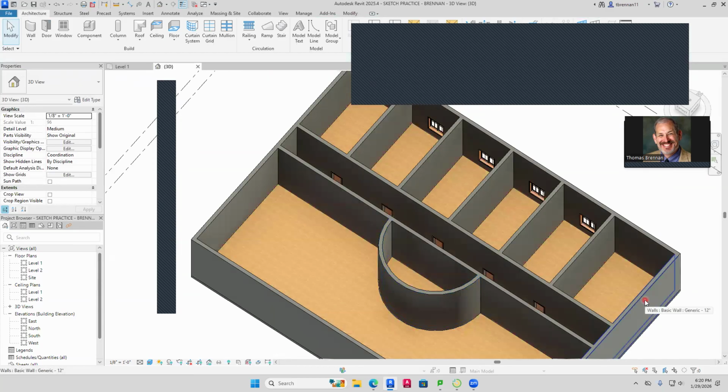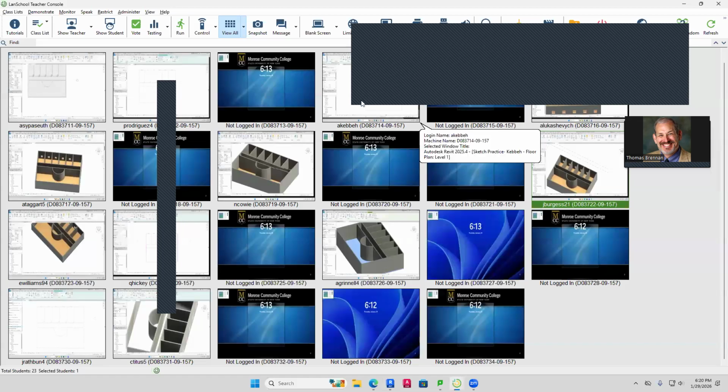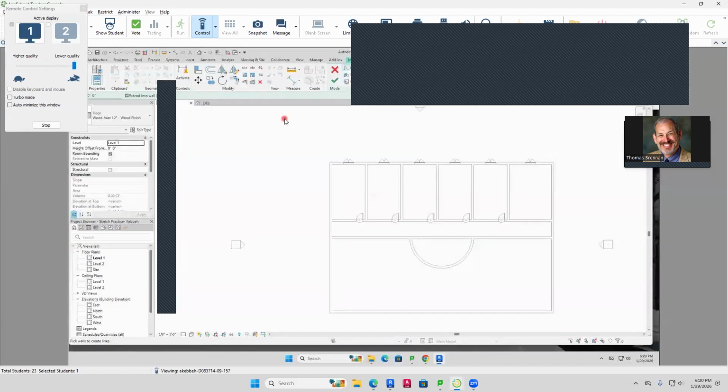Yes, sir. After you press joint, wood joint. Okay, yes, so you click on okay. So what you're gonna do is you're gonna click on the rectangle tool. Okay, so click on rectangle, then pick the far left top. Yep, click there and bring it down to the far right and click there and hit the green check mark.